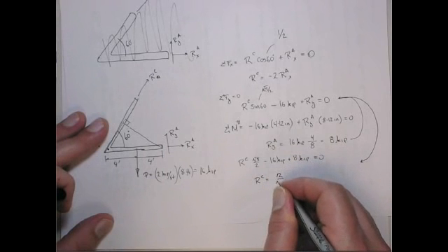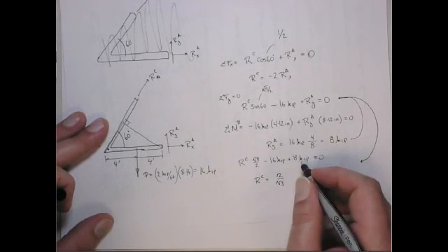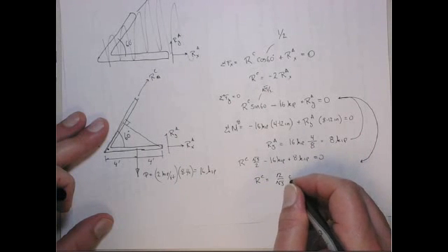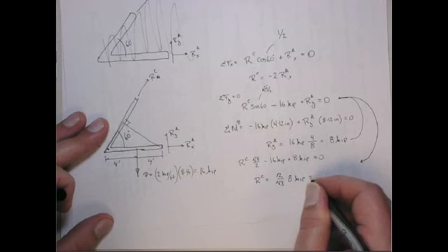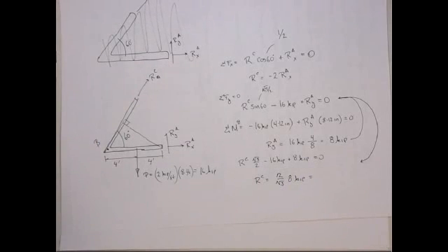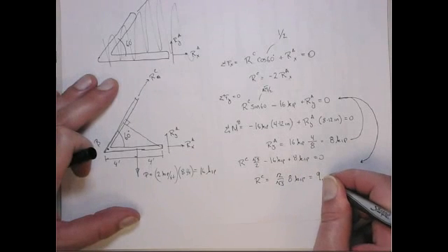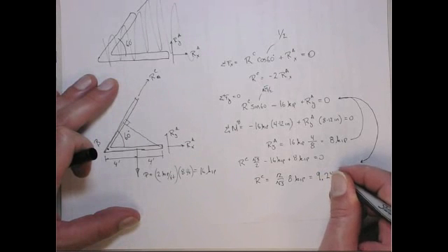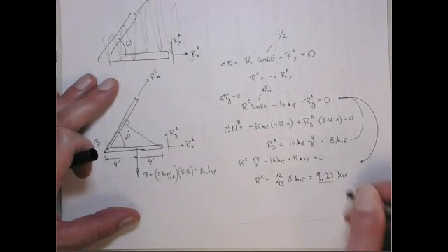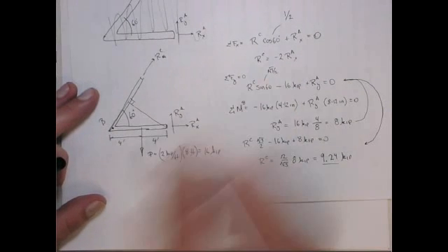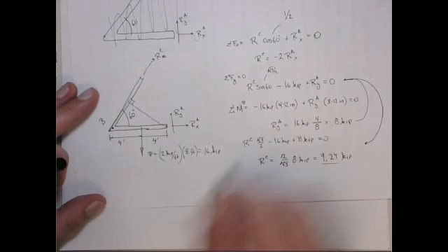2 on root 3. This is a minus 8 kips, bring to the right-hand side. That becomes a positive 8 kips, right? And that equals 16 divided by root 3. Oh, wait a second. 16 over root 3. All right. So that's 9.24 kips. And then the last one we can do is get the reaction in the x direction at A